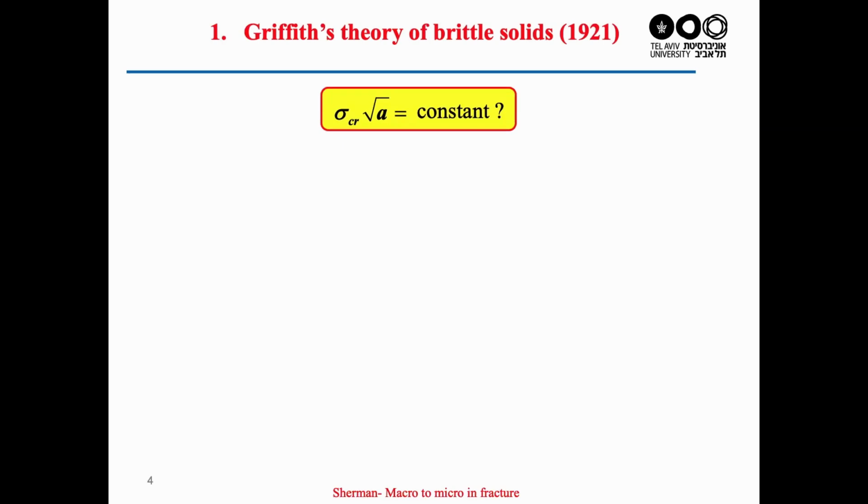Griffith claimed that sigma critical, the tensile strength at which the crack initiates, times the square root of a is constant, and we will examine it also.